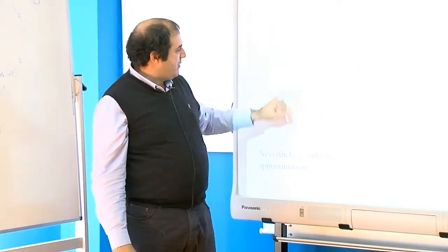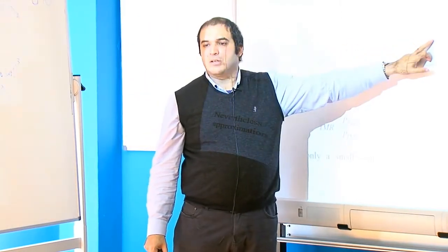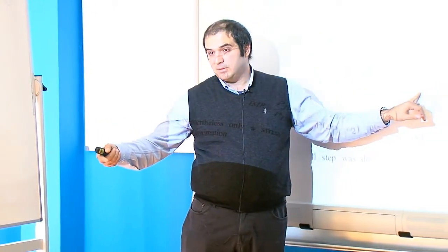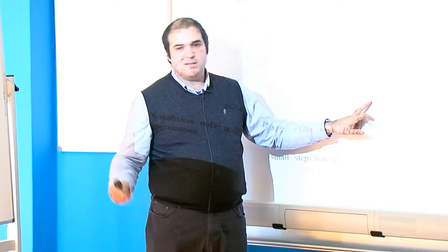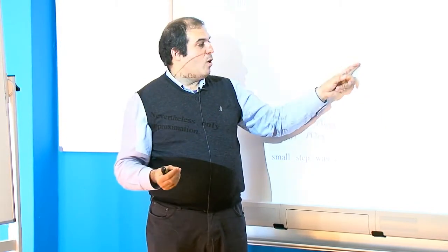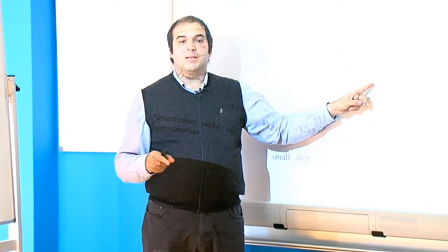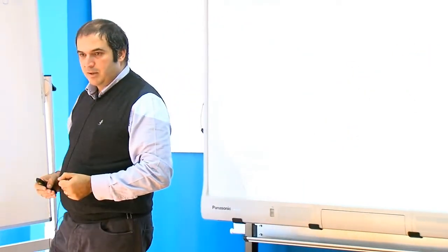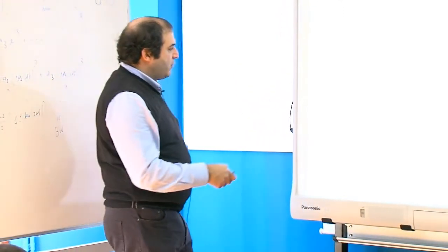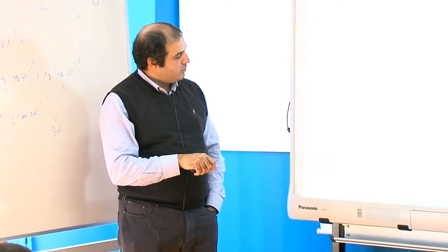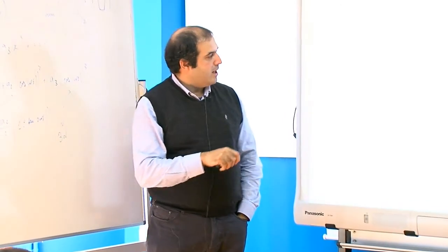And you can have third order intercept point. You can also have second order intercept point. This is the signal going up at second order. Okay, second harmonic if you want. In this case, it's not second harmonic, it's another second order that appears at the video bandwidth or baseband. And why is this curve important? For mixers. Very important for mixers, because you can know where they start to compress somehow in that sense. Okay? And of course, with this, you can define what is called the intermodulation ratio, which is equal to the fundamental power divided by the intermodulation, and this can be all extrapolated from those measured curves.